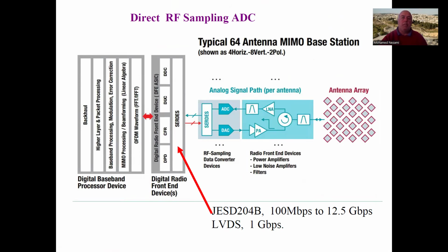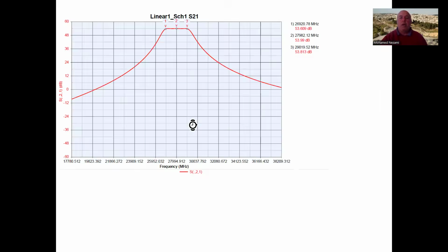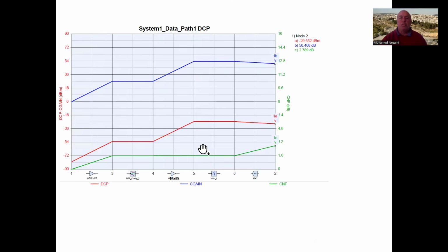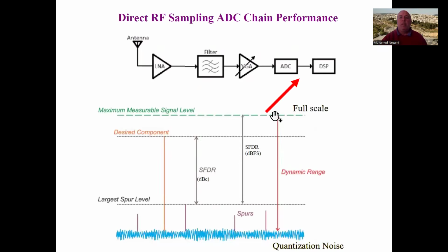Okay, so until then, we're going to go through this example in here where we can show this using SystemView, and then finally we're going to end up by looking closer at the ADC signal dynamic range, and look at the signal to noise ratio and the harmonics, spurious, aliases, and start building a method by which we can actually design a direct RF sampled receiver.